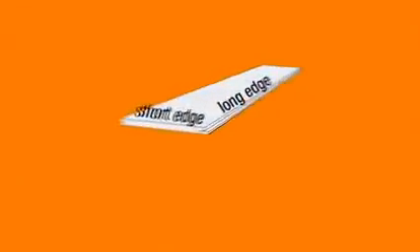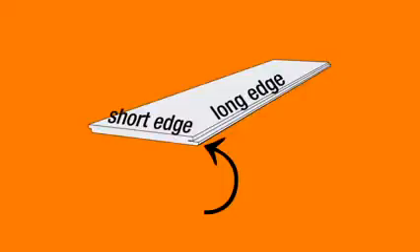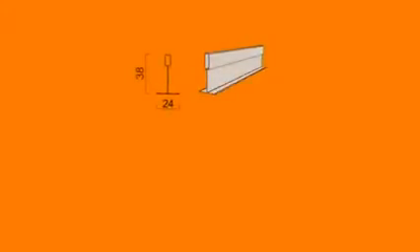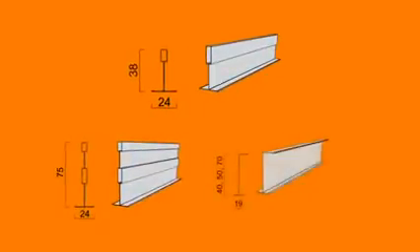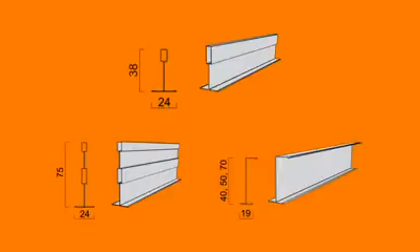The direction of installation of the selected system type F2 always follows with the so-called AW edge facing the installer. The tiles should never be left unsupported. Have a suitable reinforcement profile to hand and within reach. The reinforcement profile is now installed and stabilizes the tile. Different profile sections are available depending on the corridor dimensions.